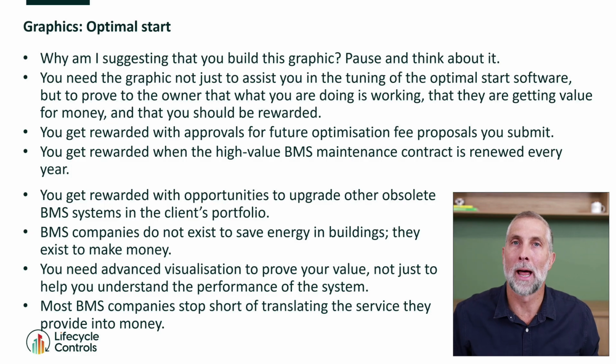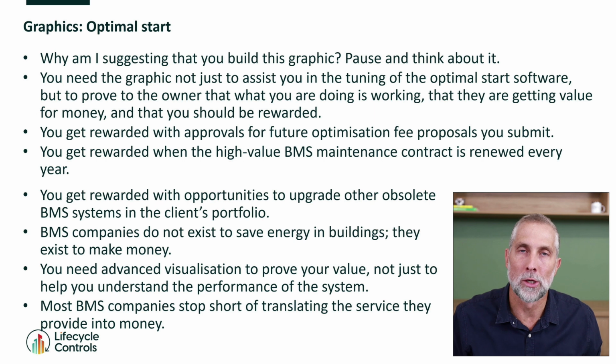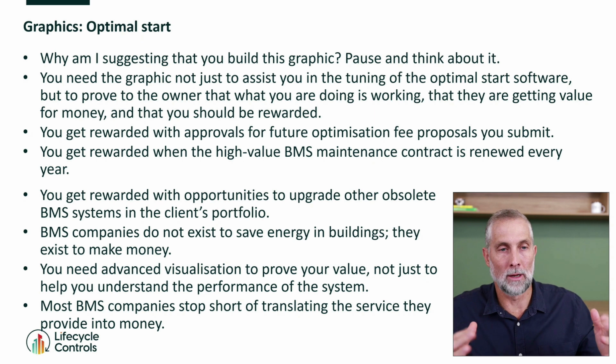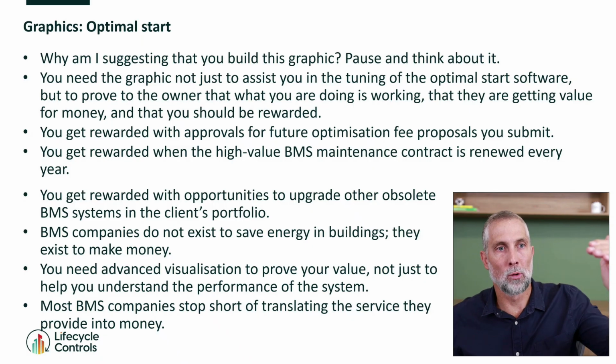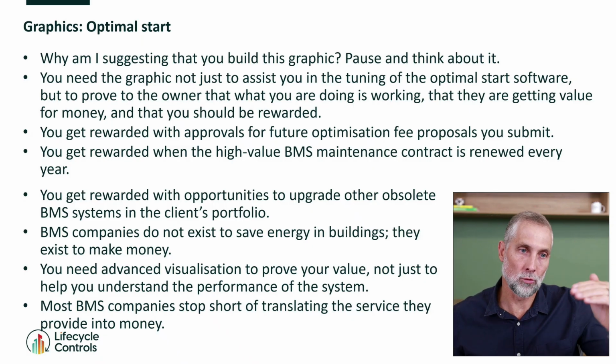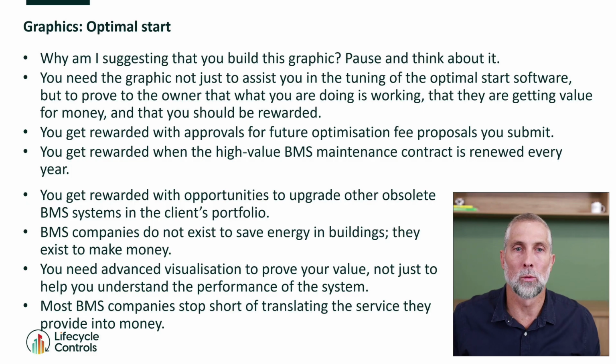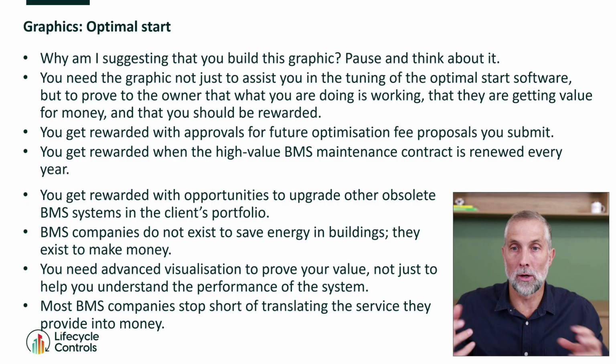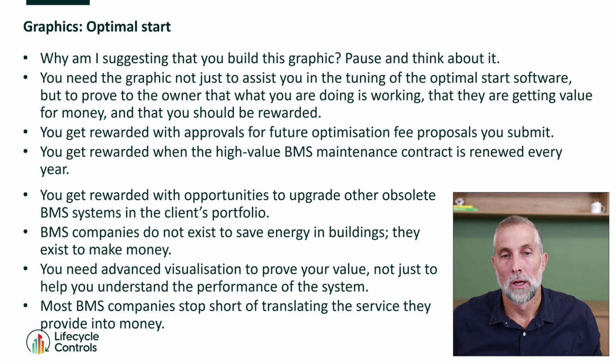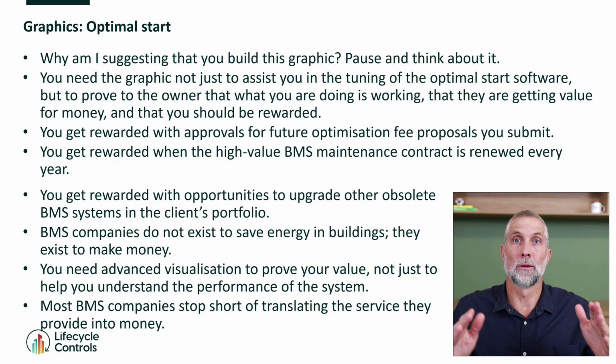And then I say to you, well, while we're here, can you prove that your air handling unit supply temperature reset strategy works and your supply pressure reset strategy works? And you're like, yeah, sure. And you'll show a graphic with the high pressure set point limit and the low pressure set point limit, and it's resetting. And I'll be saying, well, where are the demand points? Where are the VAV damper positions? How do I know the dampers are responding? I haven't mapped those points.